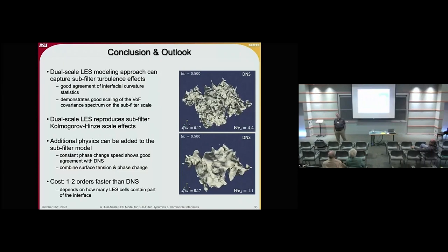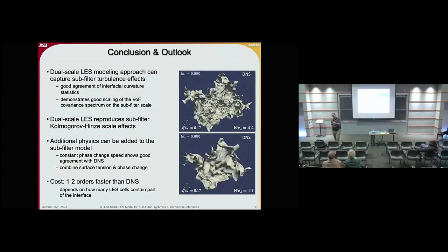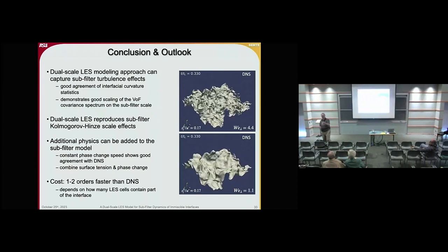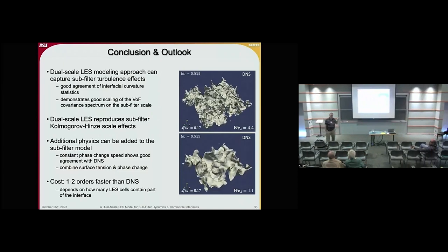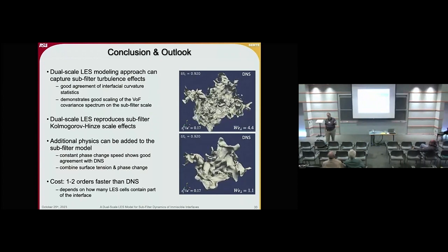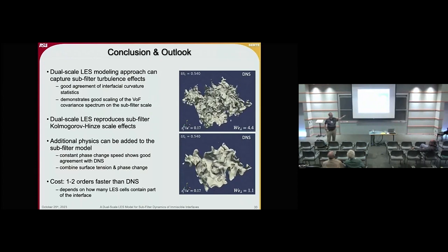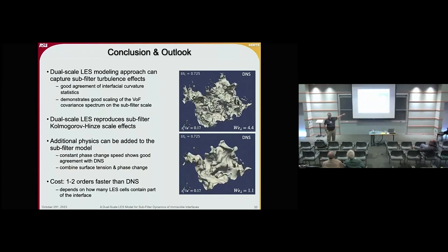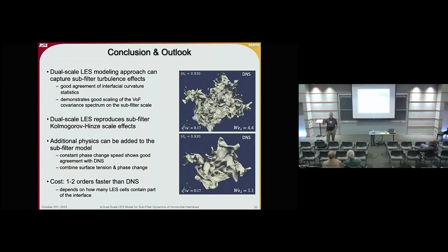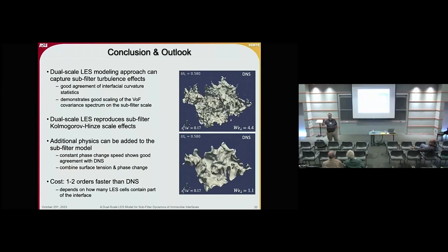Yes, so in a sense, I glossed over the entire thing. I said I have a constant sigma, which, if you inject into combusting devices with strong temperature fluctuation, is not obviously the case. And now how can you do that? It's kind of hinted at with the evaporation. So what you would have to do is take your mean LES filter thermodynamic properties.